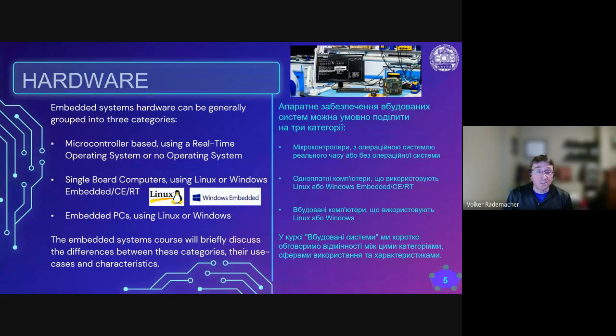And often they contain PC-untypical interfaces, for example, RS-485 or CAN, in addition to Ethernet. They have better expandability than single board computers, but limited compared to regular PCs. For example, regular PCs have PCI Express slots. Embedded PCs usually only have either 1 or 2 or none.